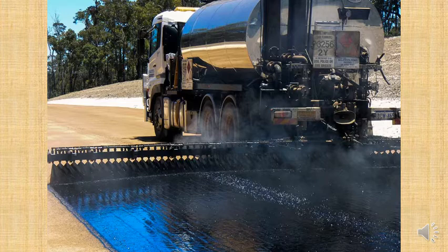Now if we were just doing bitumen, we wouldn't be able to do that, because bitumen on its own is like a big thick toothpaste at the best of times, where we'd spend many months trying to roll out the bitumen over the road. It's just not feasible. Mixing it with the kerosene gives it that lower viscosity, which makes it runny and workable.